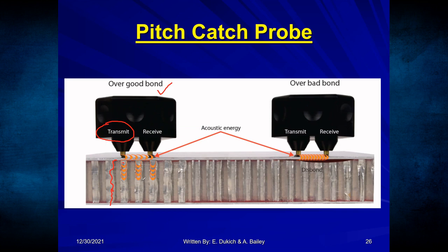So the thickness of the specimen tells me the frequency that I'm going to use for my technique. I transmit the sound through, and the receive side can tell the difference between the transmit and the receive. So any interruption that stops that energy will give us a signal response, because I'll have an imbalance between the transmit and the receive.